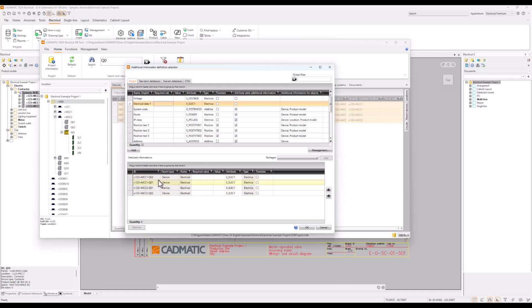Now all these devices might want the same value, so you want to fill in them. Now you have to do it one by one. Type in 3NO 1 NC, so 3 normal open and 1 normal closed. Copy the text and fill it for the value fields, like so. After the values are set, you can press OK.